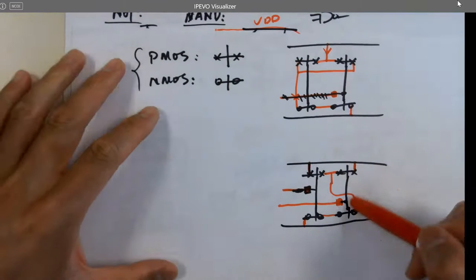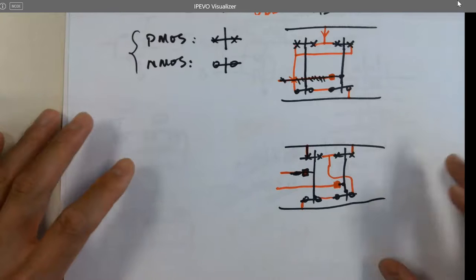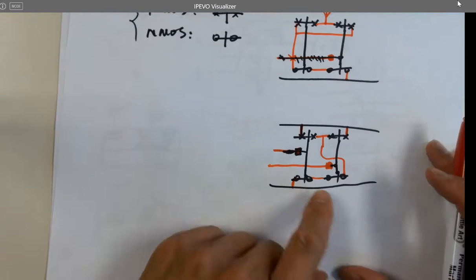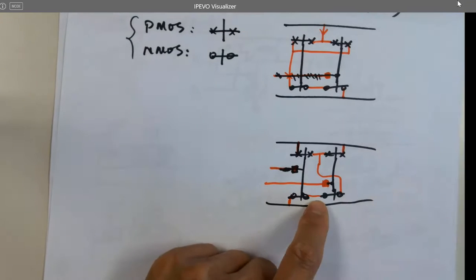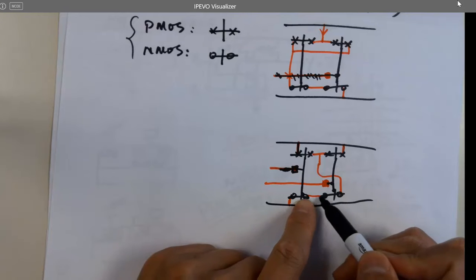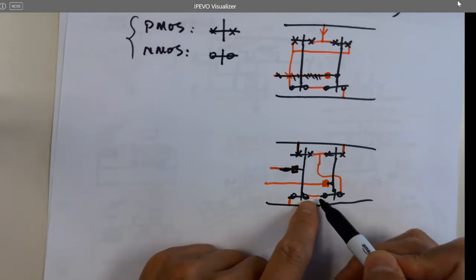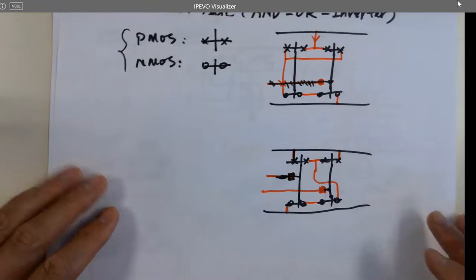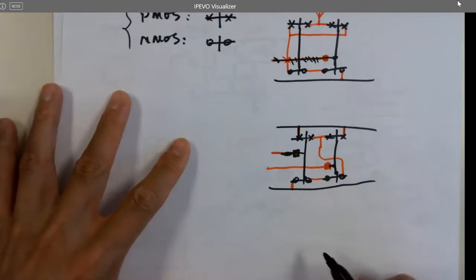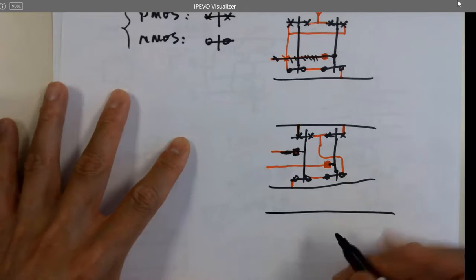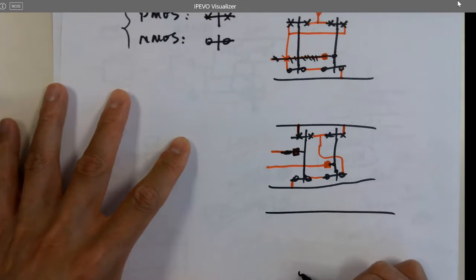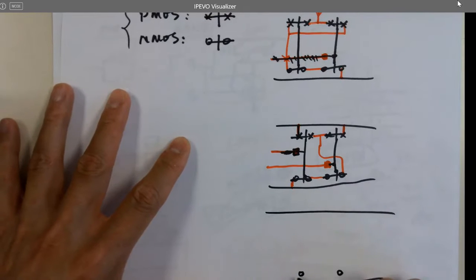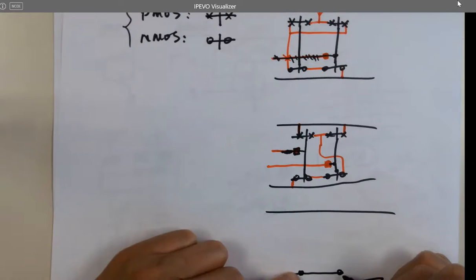I mean, the routing is okay, but like this one. So I have a via going to metal, go to another via. They are the same voltage node, right? Do I need the 2 vias and metal? No. So what you can do here? So what actually we do is just 2 diffusion nodes, just 2 N pluses, N plus 1 and 2 N plus.